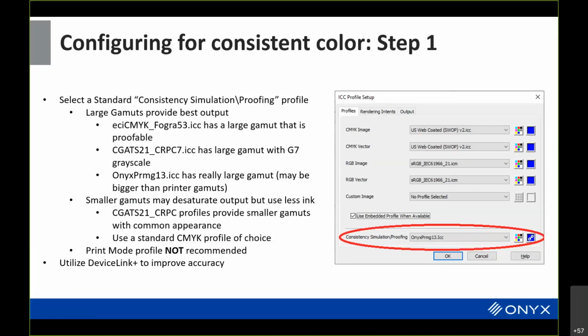Now, if we use a simulation profile, we actually do two steps. The first step goes from the input profile to the simulation profile, and then from the simulation profile to the printer profile. So if we're just using profiles, we're going into and out of PCS twice, so we've doubled the transfer fee for converting colors.